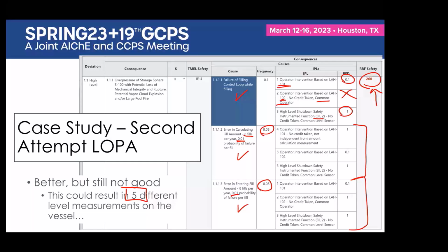So what did we do? I said, well, your procedures say to do a LOPA, but your procedures also allow you to do something that we at Conexus call a focused QRA. So if our LOPA is generating excessive recommendations, we can do a more detailed quantitative risk analysis to sharpen the pencil and get a more realistic assessment of the actual risk. And we will go ahead and run a fault tree analysis on this to determine whether or not we can get by with fewer transmitters. And that's what we did.